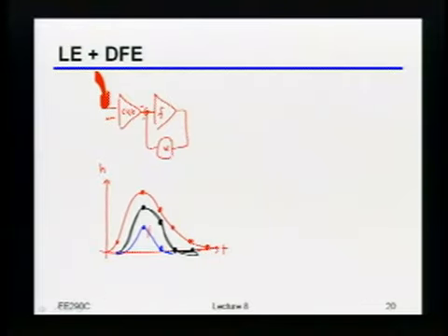But the trick is that crosstalk usually is at a fairly high frequency, right? Because it's usually capacitively or inductively coupled, right? So just by being able to back off on the bandwidth of the CTLE, I'll be filtering the crosstalk more heavily, right? It's not that it's going to go away, but at least I won't be amplifying it as much as I was in the past. Got it. Does anyone ever do MIMO with crosstalk?